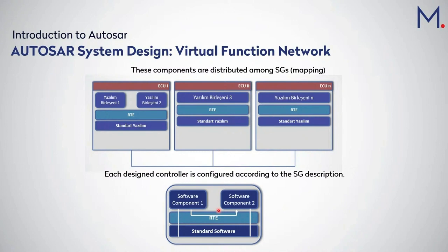This is a choice, and this choice is made in RTE, and RTE knows how your software modules are communicating with each other. So RTE is executing this mechanism, this functionality, and it is the center of this functionality. It's the heart of Autosar. That's why it's the heart of Autosar.